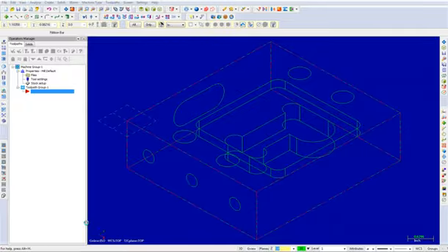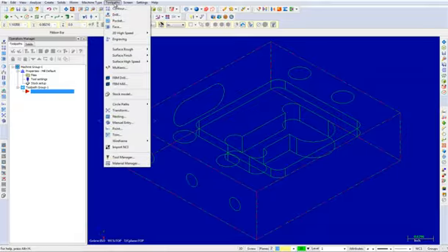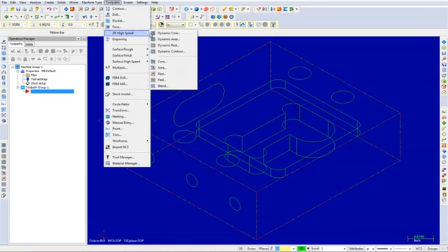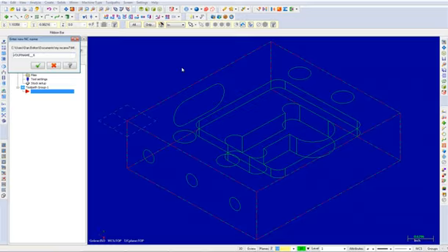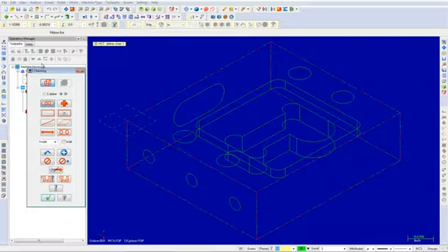That being said, select Toolpaths, 2D High Speed, Area. When the new NC Name dialog box appears, select the OK button. When the Chaining dialog box appears, select C-plane. Leave the chaining method set to chain as shown.